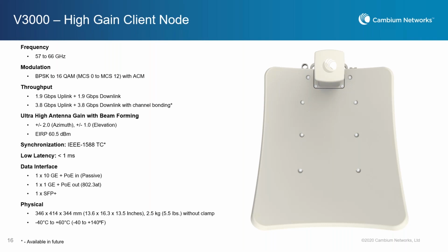For a radio without beamforming, your beam width is very narrow, so if your installation shifted for whatever reason, a little twist, then you have to revisit the site to do the adjustment. With beamforming, even if it's only 4 degrees, this helps a lot. More than that, the latency is very small, less than 1 millisecond. Typically, it's between 200 to 800 nanoseconds. So it's pretty low latency for a point-to-point link.